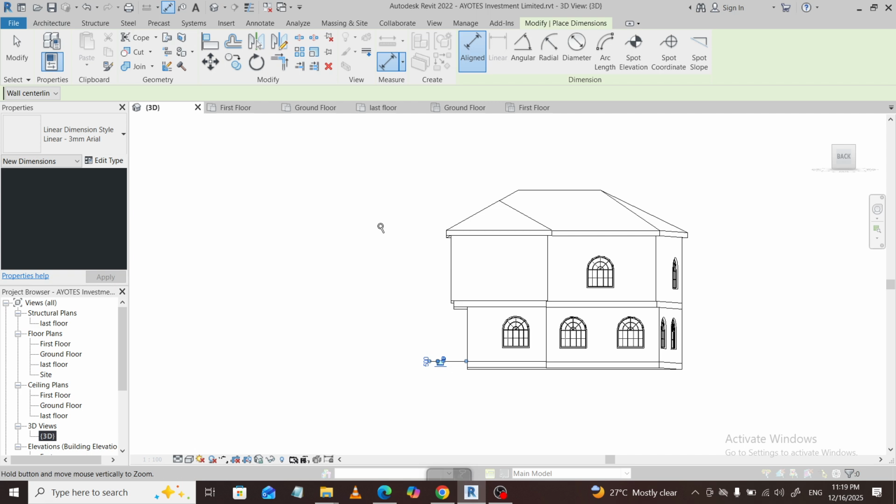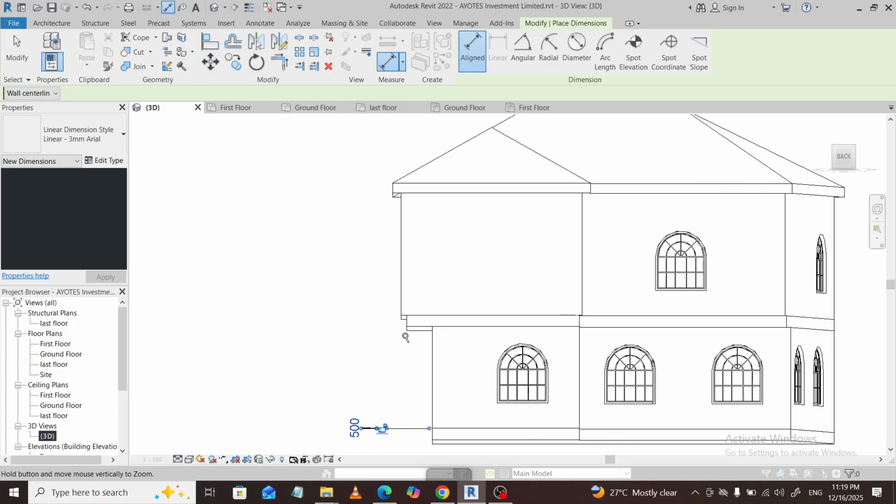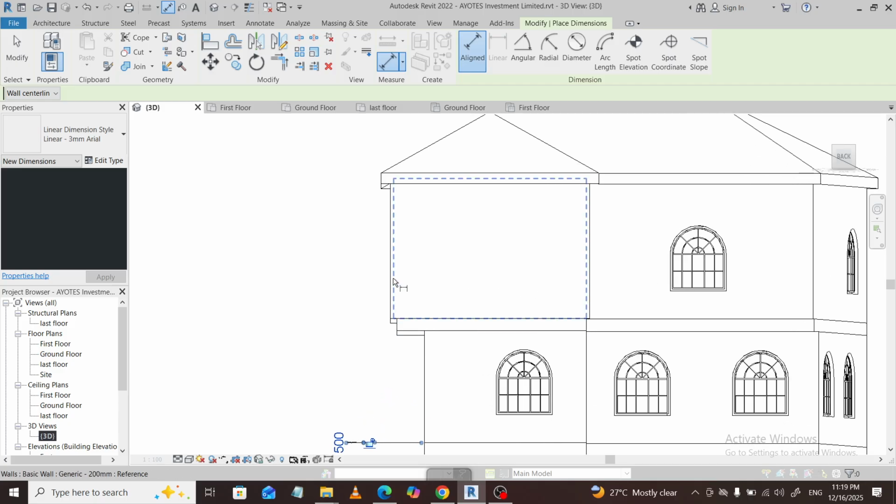That's it. Activate a 3D view, go to Modify, Measure Between Two References for straight line distances, switch to Measure Along Element for edge lengths, and use snapping for pinpoint accuracy. With these tools, verifying distances in 3D becomes fast, clear, and dependable.